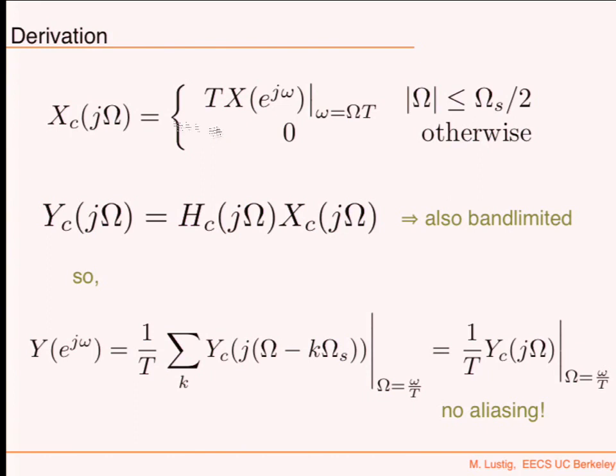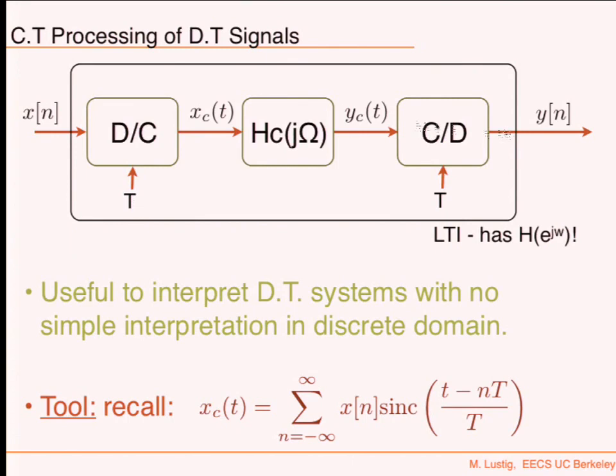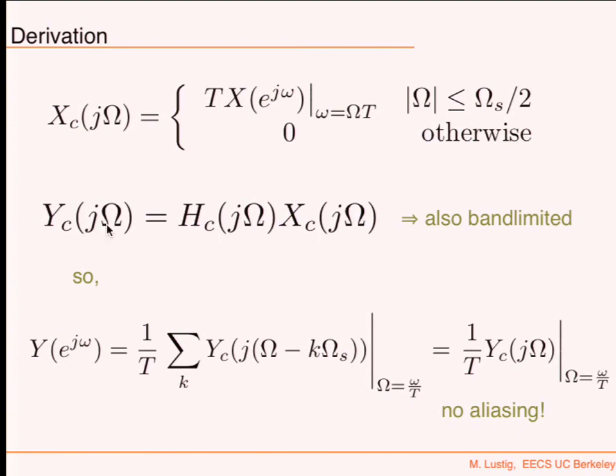Okay. Great. All right, so what is y? Remember, y is the output, right? This one. So that's before, that's continuous, and then I do the continuous time processing and then continuous signal. So what is Y_c(jΩ), the continuous one? It is X_c(jΩ), which is this, multiplied by H_c(jΩ), which is the analog, right? The analog frequency response.